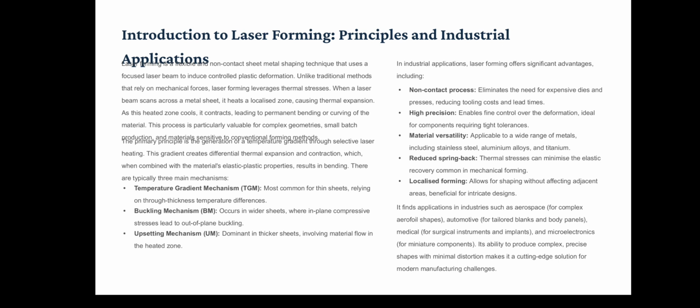Unlike traditional methods that rely on mechanical forces, laser forming leverages thermal stresses. When a laser beam scans across a metal sheet, it heats a localized zone, causing thermal expansion. As this heated zone cools, it contracts, leading to permanent bending or curving of the material. This process is particularly valuable for complex geometry, small batch production.